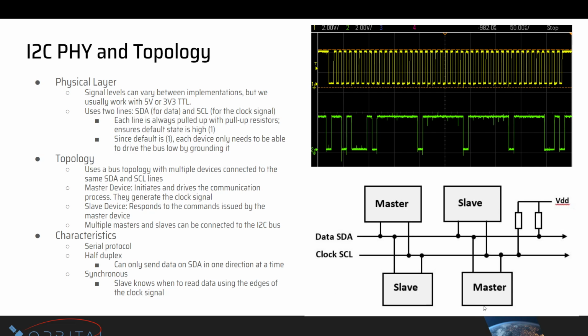And since, like I mentioned before, we have this bus configuration, we need some way to know, when data is put onto the bus, if they're trying to talk to us or to somebody else. Like in real life, you would say somebody's name so they know you're talking to them. That is similar, and here you have addresses. Each of these devices has its own address. So I would first start off with their address, and they can read it, and if it's their address, they know to start listening. If it's not, they can just ignore it.